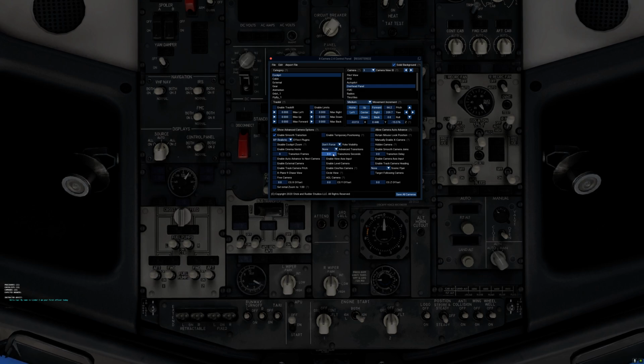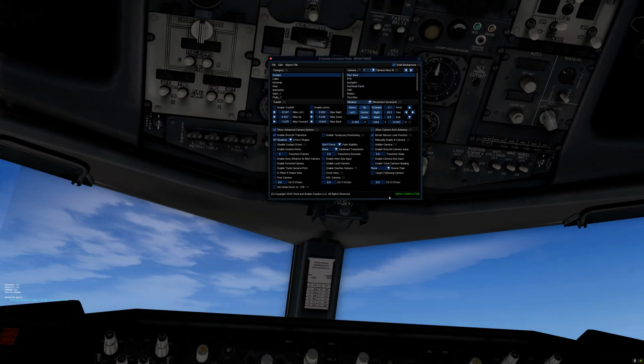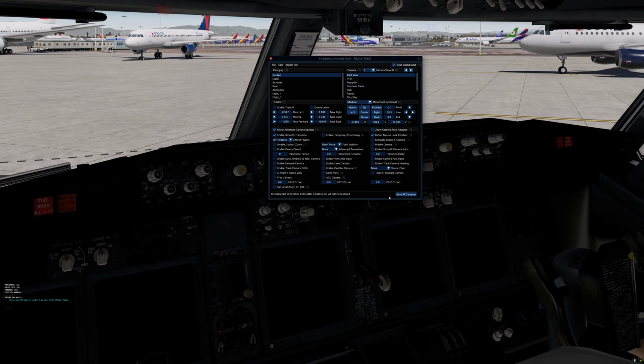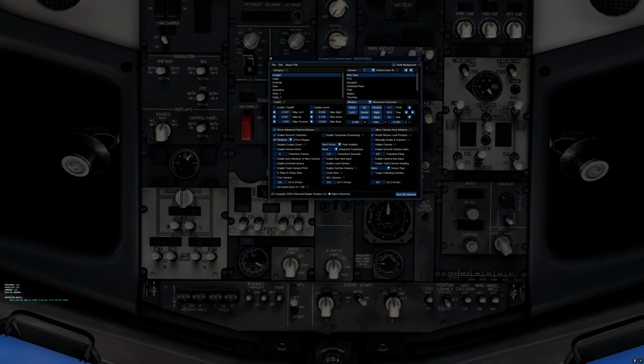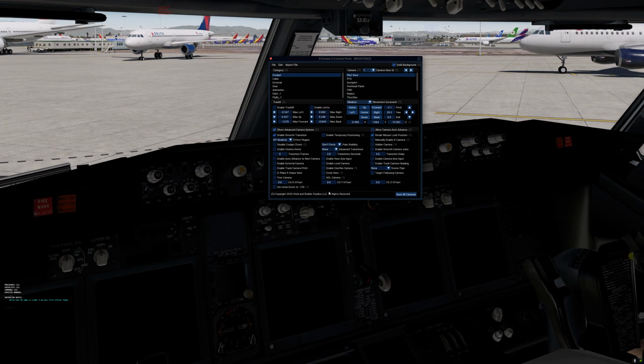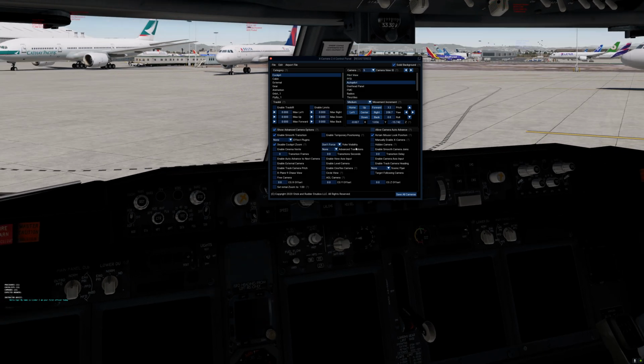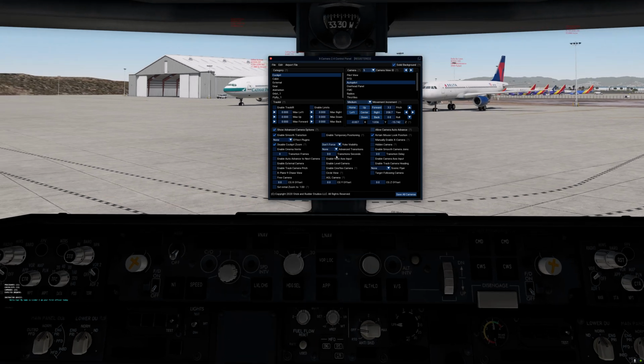I'm going to go in and change this to 2-second transition, and it'll be a gentler transition from the main view to the overhead view instead of snapping like that. But with the views that you've set up for the artificial views, having that 2-second is not as important, in my opinion. Okay, so moving on to the third row.